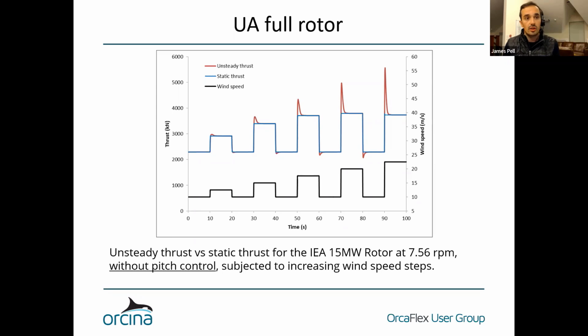Other data is also set, for what it's worth, for features that came out after the first edition of that example. So the shear center in the blade profile data is fully populated now as well. Alongside that, we're issuing a little validation document of that rotor, comparing it against the OpenFAST model from the GitHub repository. We're looking at the blade dynamics and aeroelastic response for steady, stepped, skewed, turbulent winds. The comparison is very good, I should say.